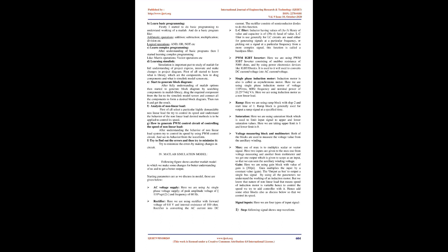2. Block diagram of overall system. We can discuss the 3 recent techniques of speed controlling of induction motor. On the basis of the third technique, that is sampled data control processing in closed loop, this whole system works. As we can see in the block diagram, figure 1, it describes the basic working of our project. First block is pulse tuner. As we want to transfer a signal to the controller block, the output of pulse tuner is applied. The controller works only on DC signal but the input signal given to pulse tuner is AC signal, so in the pulse tuner the input AC signal is converted into sampled discrete signal, that means a DC signal, by using ADC, and we get sampled data at the output of pulse tuner. Then this data is given to the controller block.